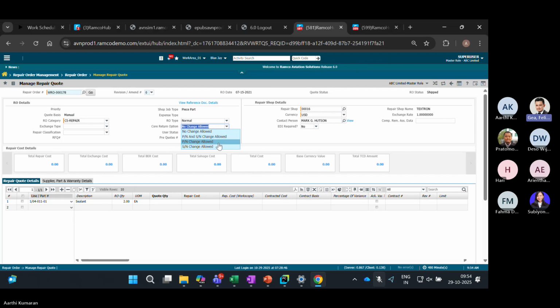So we check the order and there is no change. This is how you do it. That's it. Simple. Because you needed traceability: what was removed, what was sent, what was received, and what was installed. That can sometimes be a modified part number, or it can be a valid alternate part that you have received from the vendor. It will not change anything, but only subsequently do it in the receiving process. I think that's the question that we asked HQ as well. The part number change is a different part number that you receive from the vendor than what was originally sent. That answers that question.